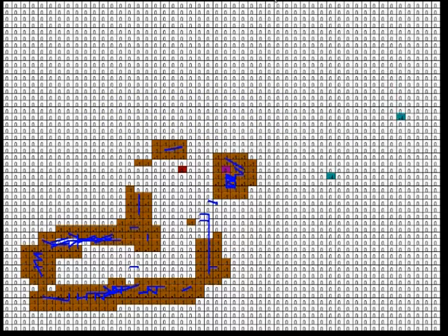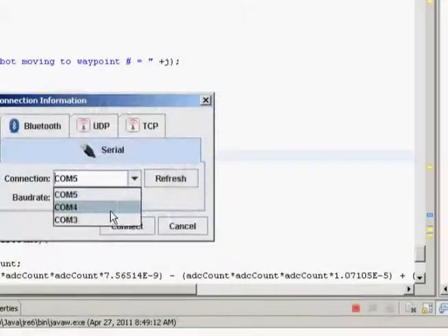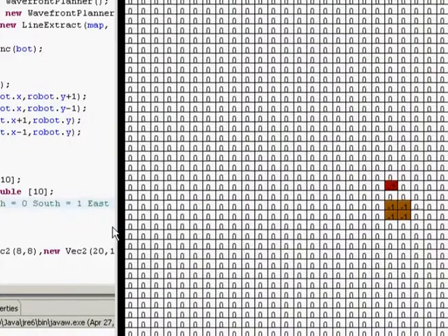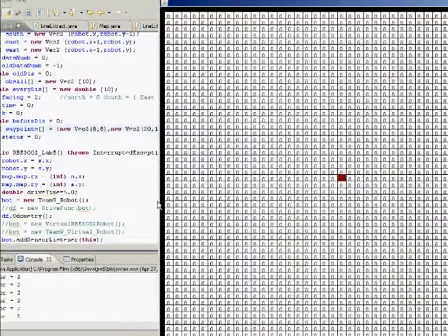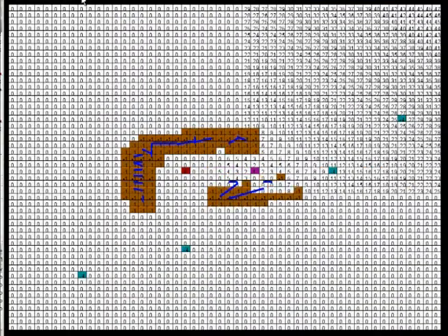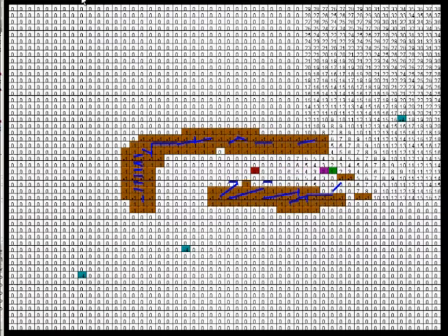We use odometry to determine where the robot is and to return its position within the GUI. We use cosine and sine with how much each wheel turned to return the position in the GUI. That's how we figure out where the robot is, and the robot is printed in purple if you look at the GUI.